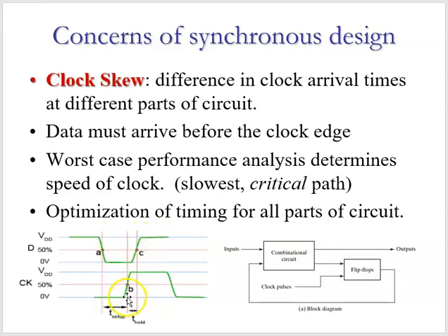The clock is going to sample that. This shows a rising edge. This is just one edge of our clock signal. It shows two edges, but the rising edge is the transition that's going to create a change in our flip-flop, in our memory element. The change from our present state over here will change to the next state on this edge. What we have here is a setup time and a hold time.